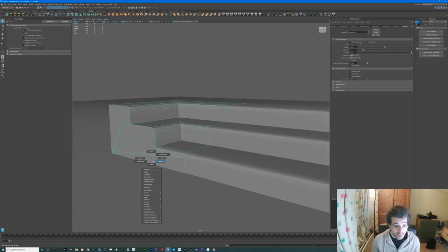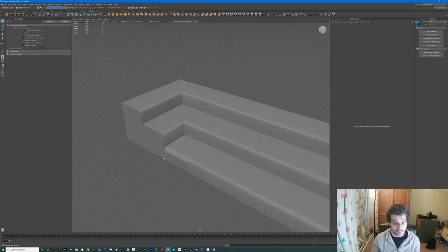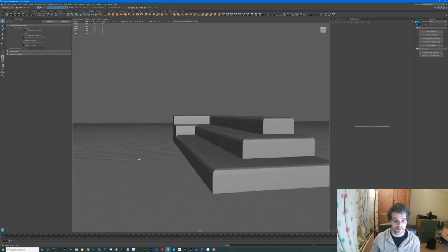This one here, let me just select these faces, face normals. I'm just coming here to mesh display. Here we go, mesh display, harden edge, and here edge, mesh display, soften edge, object mode. Okay, perfect.